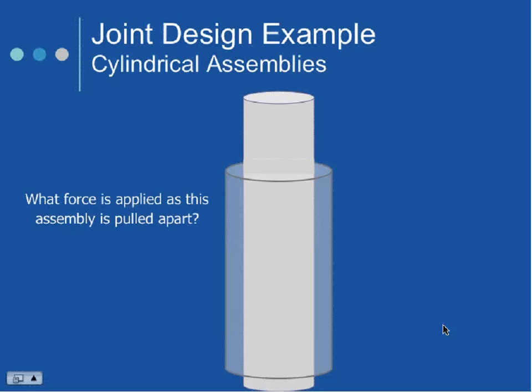Okay. Texture. Roughen the surface? So maybe you could grit blast your stainless steel in this area. What about roughening the inner diameter of the hub? It may help. Maybe not with polypropylene. Not much help with polypropylene. What else? I mean, the choice is yours. It's whatever you want to do to it. It's your design.